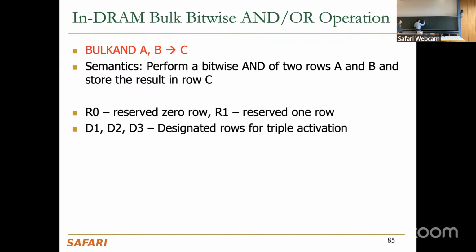A, B, let's assume D is destination. A, B can be anywhere. How do you activate 2 rows that are anywhere, right? Or 3 rows that are anywhere? You need to do 3 rows activate, actually, C. Well, that's very tough now, right? Because you need to actually have 3 row decoders as opposed to a single row decoder. And we don't want that. That's very expensive. And that's why it makes sense to actually implement something that's very small over here with a very simple row decoder that's specialized for triple row activation. So this is the implementation of the Ambit substrate.